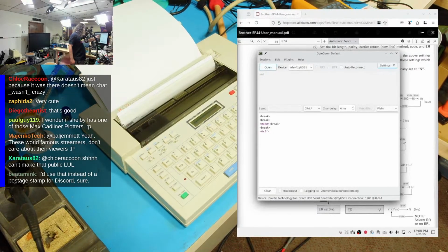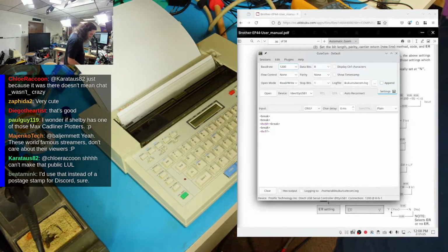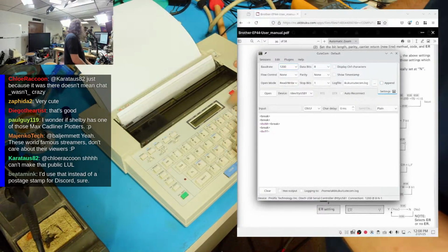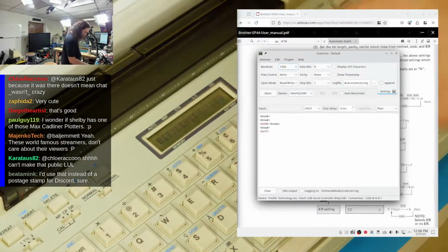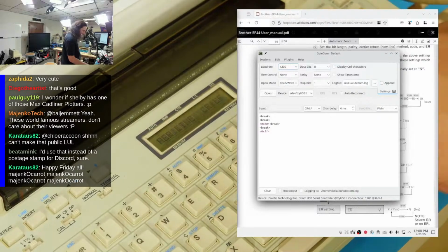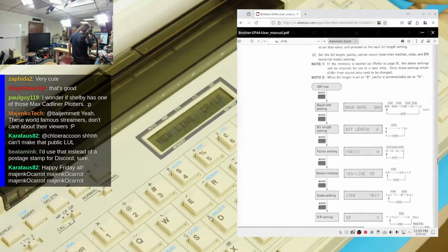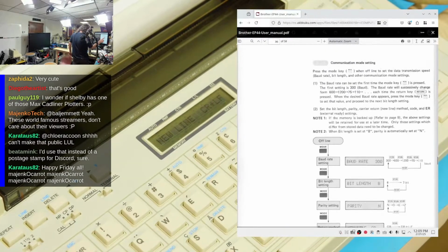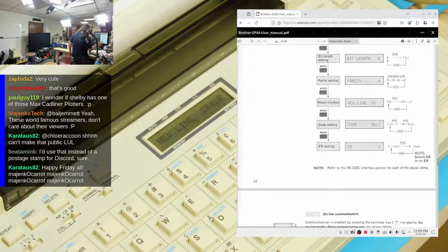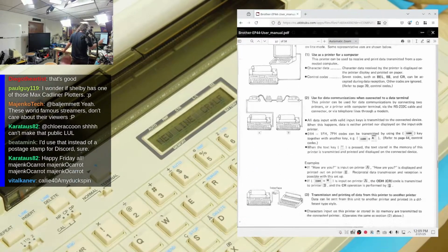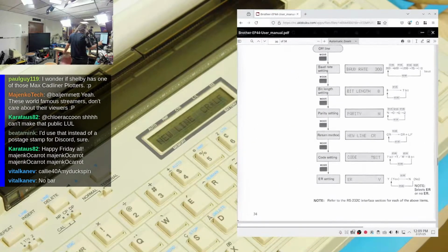All right, over on QCOM, I can see we have it set to 1200, 8N1. I can stop this, go through mode. We are at baud rate 1200 here. If I even zoom in, you might be able to see that. Okay, baud rate 1200, bit length 8, parity none. Stop bits, well, let's go over to the manual here, because I'm not 100% sure how this works. Does it even mention the stop bits? Because that would be kind of handy. Well, if it's 8, then it has to be 1, right? It can't be anything else? So let's hope it is that.